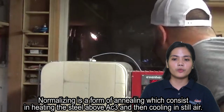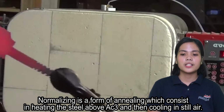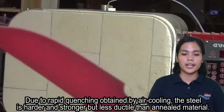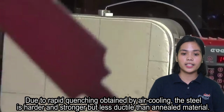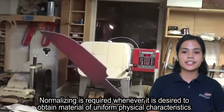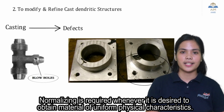Normalizing is a form of annealing which consists in heating the steel above AC3 and then cooling in still air. Due to rapid quenching obtained by air cooling, the steel is harder and stronger but less ductile than annealed material. Normalizing is required whenever it is desired to obtain material of uniform physical characteristics.